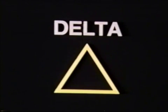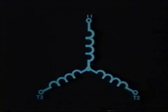There are two methods for connecting a three-phase alternator: the Y, sometimes referred to as a star connection, or the delta connection, symbolized by the Greek alphabet character, or a triangle. Most three-phase alternators today are Y-connected. With this Y method of three-phase connection, the finished leads of each of the three phases are tied together.